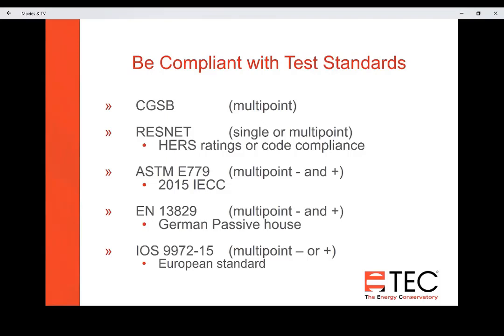We added the ResNet Chapter 8 test standard when that came out, and that includes both their single point, repeated single point, and multi-point tests. And you can do those for HERS ratings or code compliance, and they do make the adjustment for both temperature and elevation.